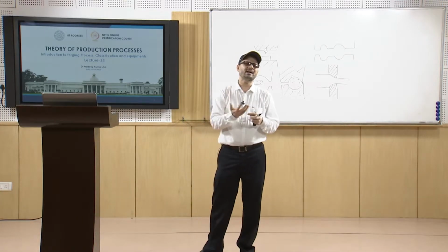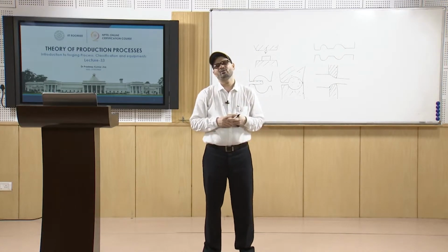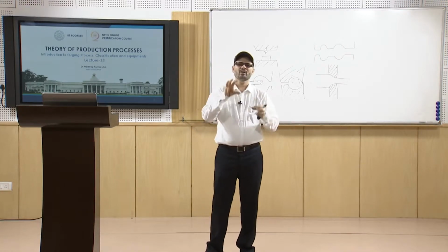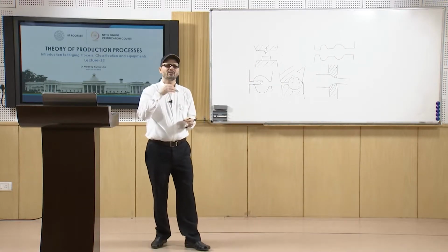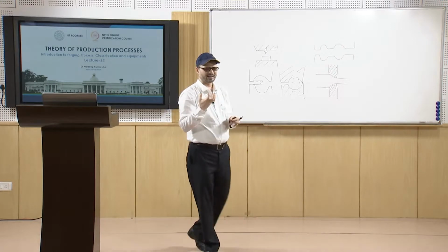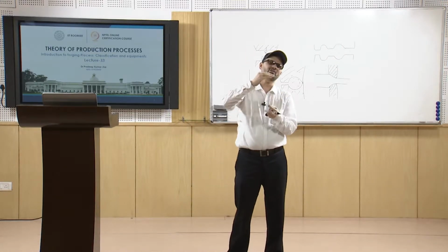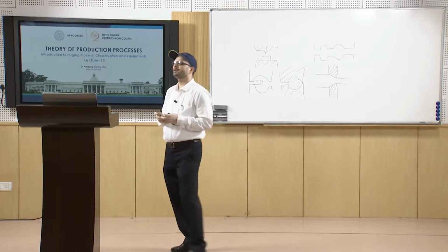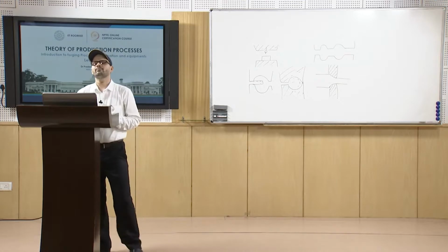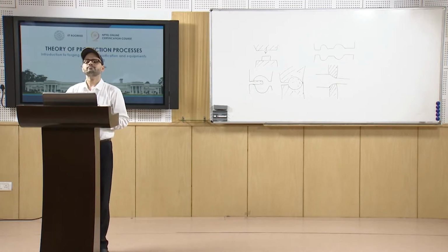Before that you have all the operations required where the material goes to different pockets. Somewhere you require larger material or the thickness is more, and somewhere it is less. This way you have different operations in closed die forging.